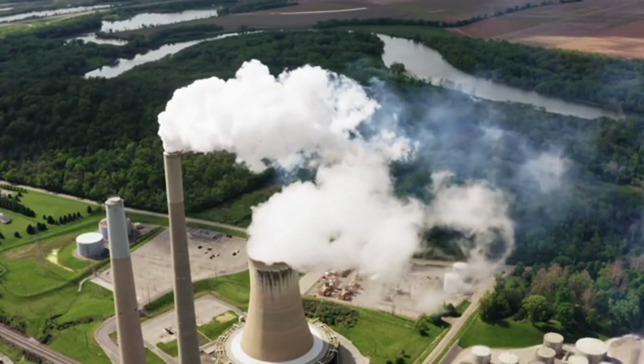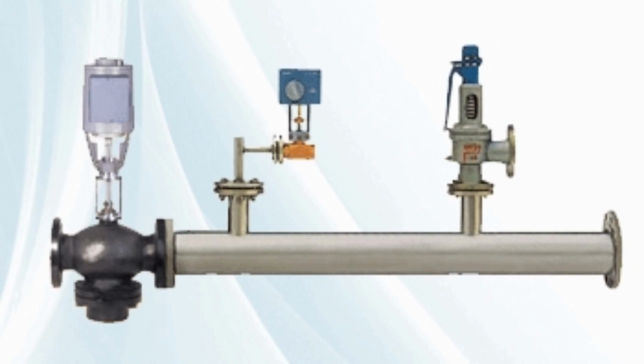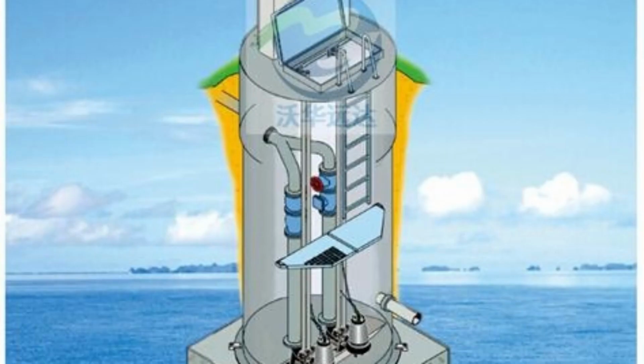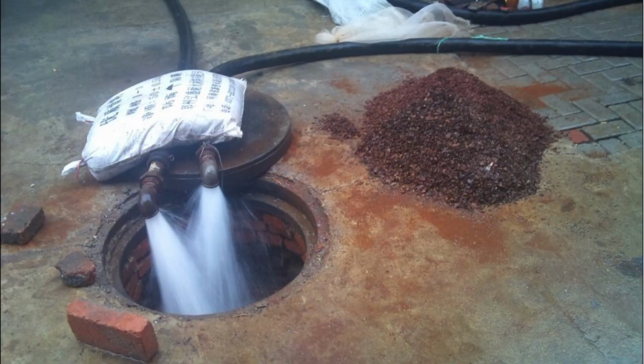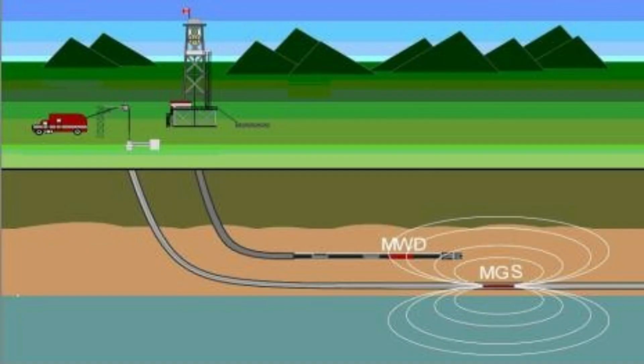Steam-assisted gravity drainage, SAGD. Currently, most in-situ operations use steam-assisted gravity drainage, SAGD, which uses well pairs, two wells, an injection well and a production well, drilled one above the other, to recover bitumen. The injection well is drilled vertically into the deposit, then turned 90 degrees and drilled horizontally. A second well, known as the production well, is drilled deeper than the first, paralleling the horizontal portion of the first well. Steam is injected into the